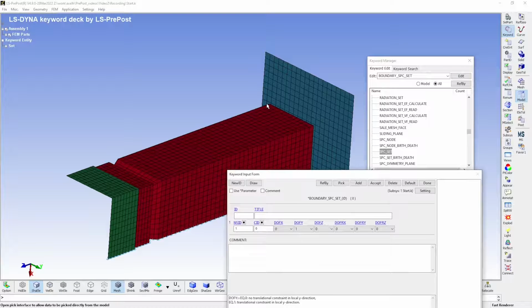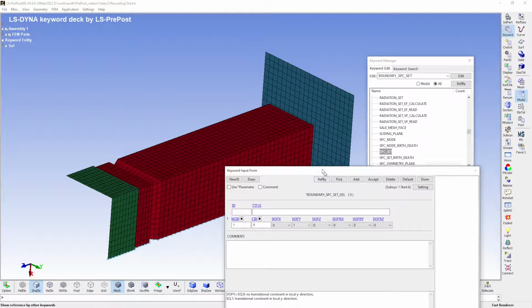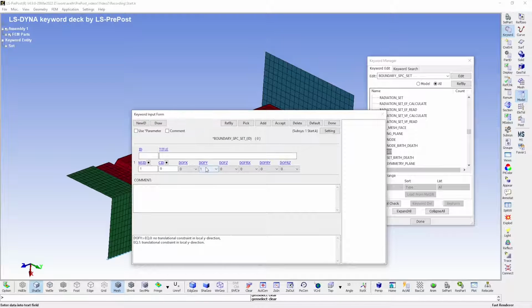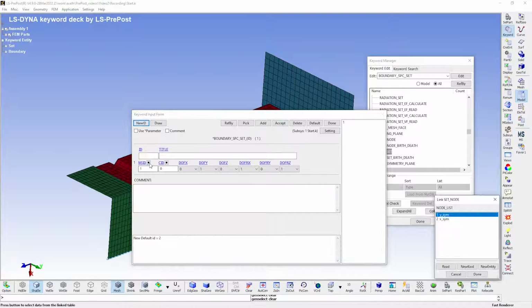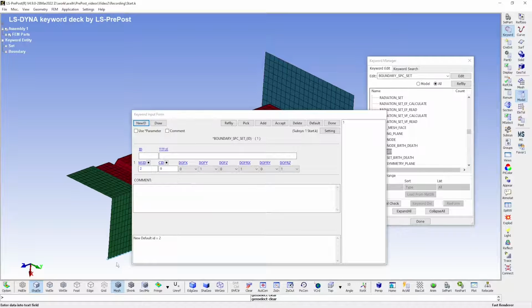So since this is the y direction and there's the rest of the tube here, we have to put a constraint on the y translational degree of freedom, as well as these two rotational degrees of freedom, since these are shell elements that we're dealing with. And we'll also create one for the symmetry in the x direction, which of course we here must change these. Oops. So it should be like this then.